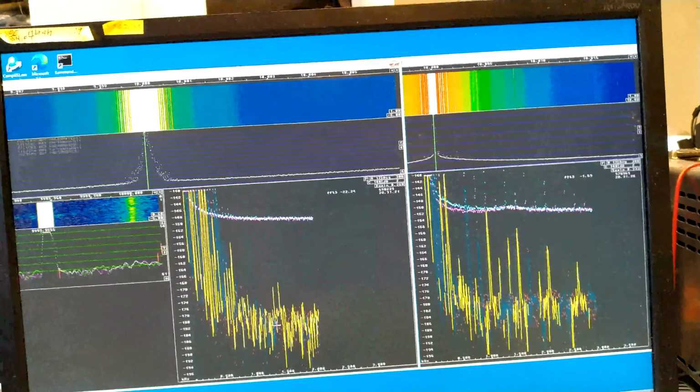1 hour and 15 minutes. The SDR IP has improved by about 2 decibels. Now minus 182 at 15 kilohertz, while the sound card at 15 kilohertz is about minus 179, and that is a 3 decibels improvement for about 4 times more time. So it seems I'm reaching some kind of limit with the SDR IP, while the sound card still can go a little bit further down.